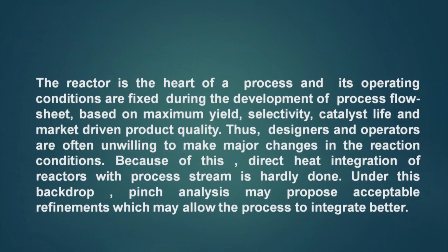Thus, designers and operators are often unwilling to make major changes in the reaction conditions. Because of this, direct heat integration of reactors with process streams is hardly done. Under this backdrop, pinch analysis may propose acceptable refinements which may allow the process to integrate better.